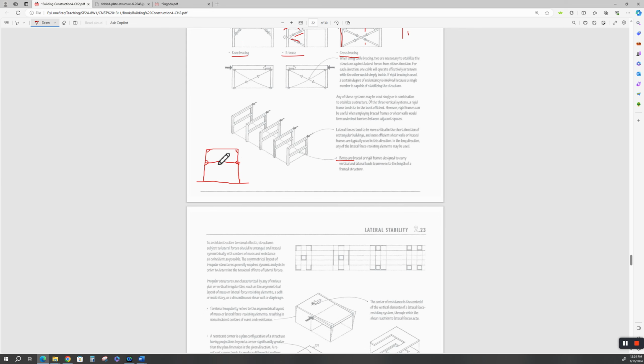Well, assuming we don't need this height for the full use of the building, then we have two rigid frames, right? You basically have a two-story rigid frame. So this reduced the length of that column. And if you'll remember the section on columns, what happens if you reduce the length? The column of a given size can carry more load, right? And so that's one column span. All right. So this can carry more lateral load that way, and it can carry more load this way.